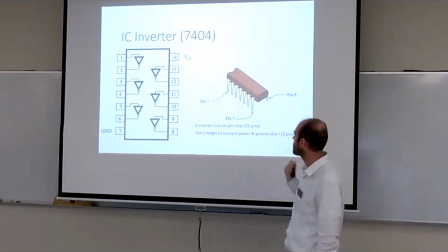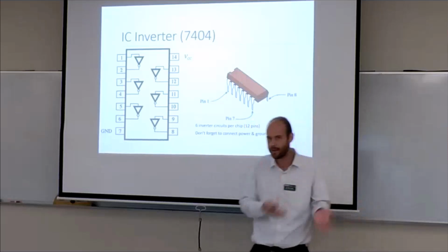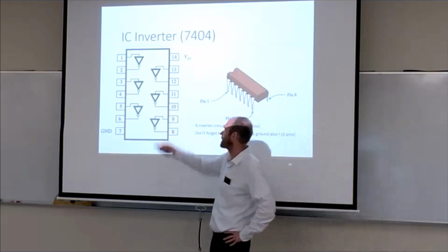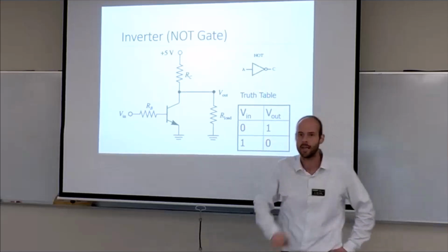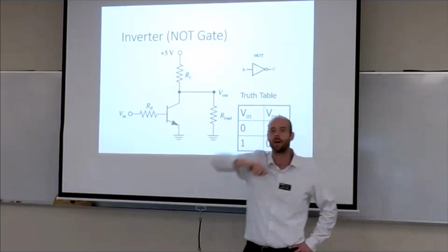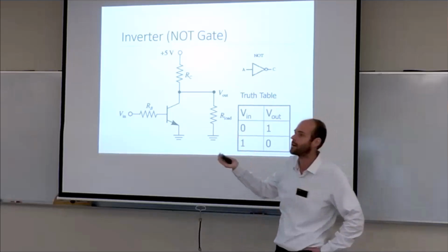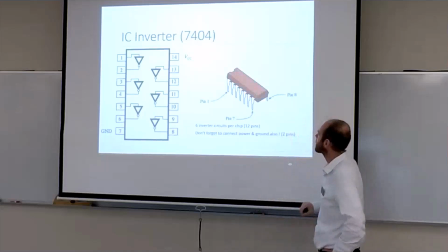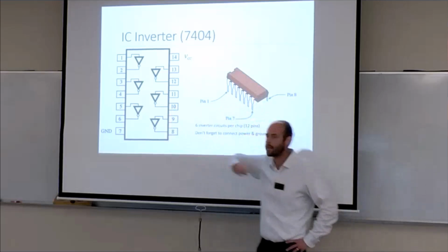Historically, all of these type of functions were done with physical chips. And when I say historically, I mean decades plus. Chips have contained a number of logic gates. This is our inverter logic gate here. This triangle with the dot on the end, we'll refer to that as the inversion bubble. And you just have one input to an inverter, it comes out inverted, right? If you had 8 of these in a row, you can invert 8 bits at once. It's like our tilde operation that we had over in C when we flip all our bits from 0 to 1, and so forth, or 1 to 0. Complement the bits.